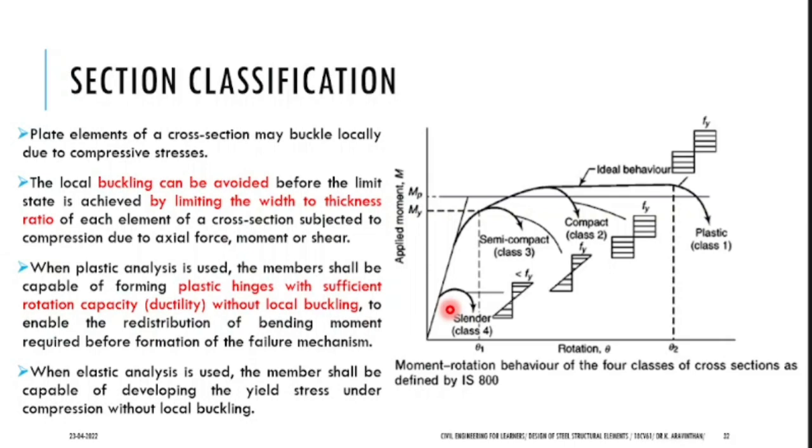What is the use of plastic analysis? In the previous class I gave an example of how a structure should fail. Making a good structure without failure is one part, and deciding how the structure should fail is the next part. I showed you a picture of a tall structure which is collapsing, not immediately, but step by step. This is a mode of failure. You are directing a certain type of failure, and this is known as plastic analysis.